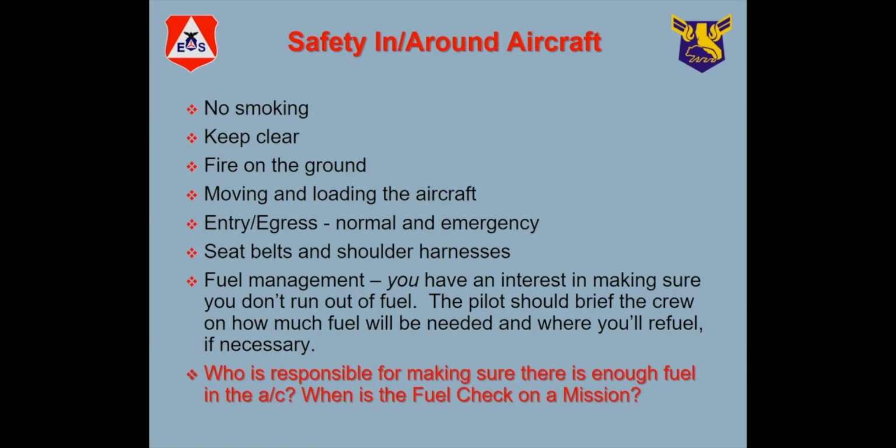Just stay clear of the propeller arc, particularly when you're pre-flighting and you're preparing to pull the aircraft out of the hangar or push it back in, and you're talking about using the tow bar. Get to the side. Colonel Denisick is absolutely fanatical about that, and I have to give it to him. It's made me aware, so keep that in mind.